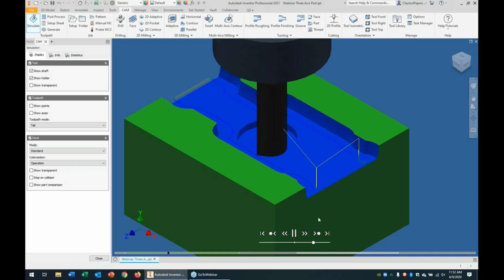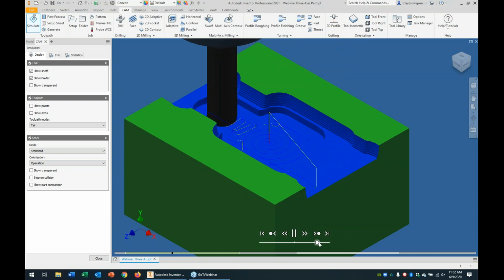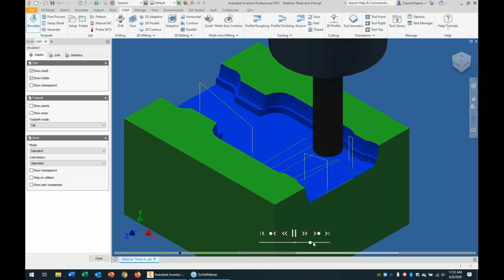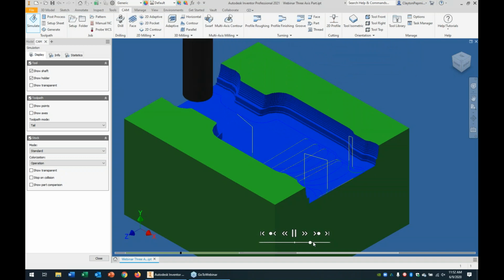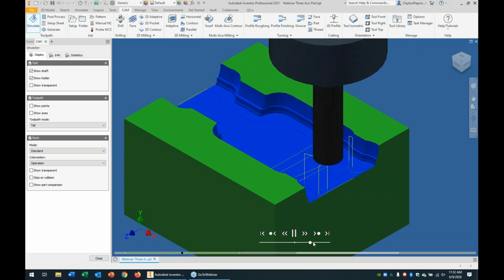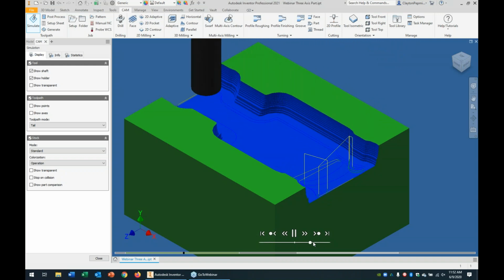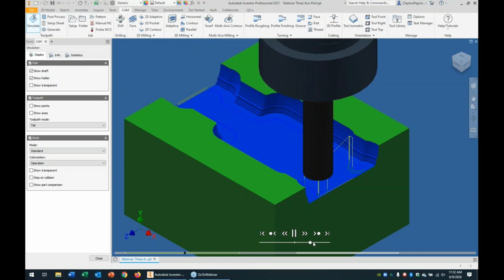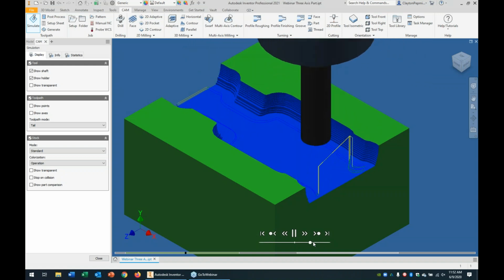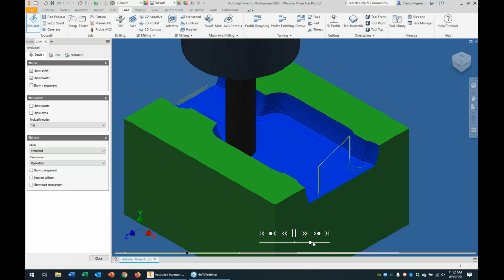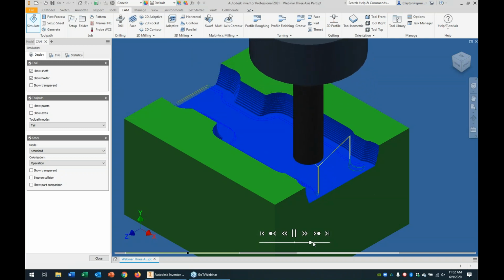I go in a little bit deeper. Try to speed this up a little bit. Again, there's the original rough, and here's those 3 extra passes I'm taking. Because I don't want to come in here with a small finishing cutter and be hitting those stair steps on that sidewall. By taking just a few sidewall passes, I'm eliminating those giant stair steps where my finish cutter is not going to be quite as affected by the stair steps that are going on.